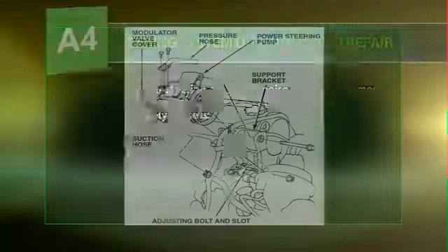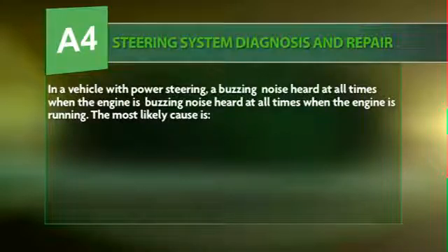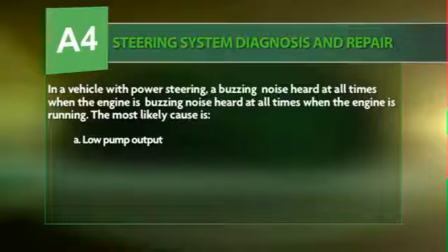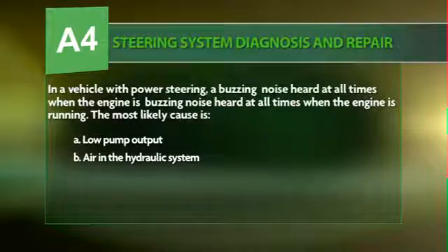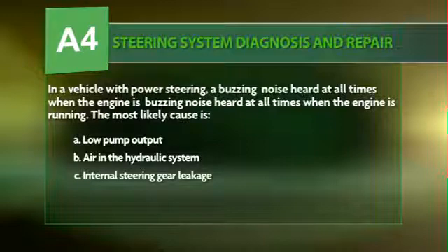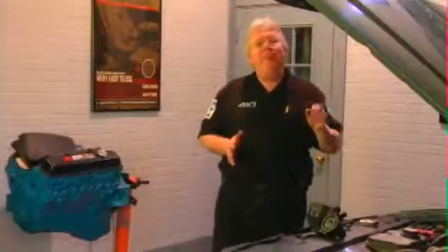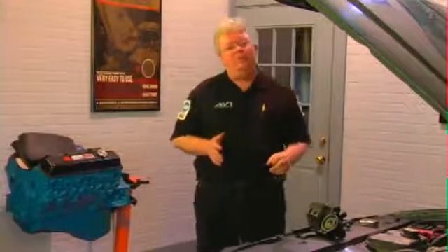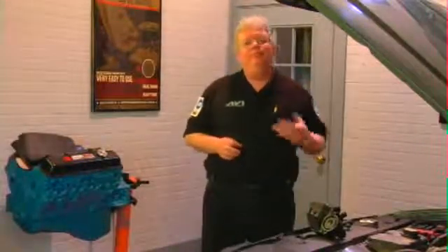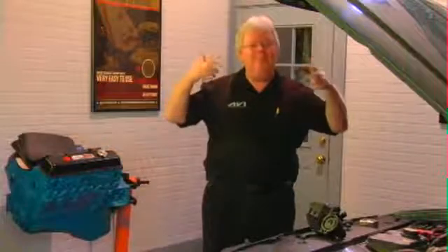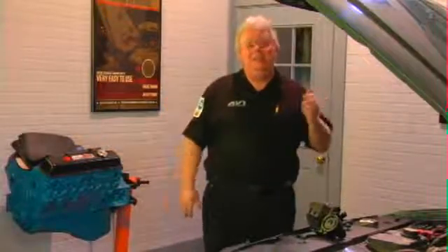Next question. In a vehicle with a power steering system, a buzzing noise heard at all times when the engine is running. The most likely culprit is A, low pump output, B, air in the hydraulic system, C, an internal steering gear linkage, or D, normal relief valve operation. Well, that's a very annoying symptom that a lot of customers really pick up on. The frequency of it is within most people's hearing ranges, and it just drives you crazy.